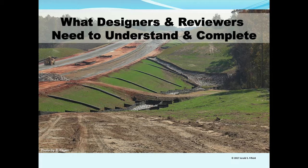So this is actually a great photograph because it shows a lot going on in it. And this is what we're trying to strive for: BMPs that are working in conjunction with the actual project itself. I mean, you can see they're working up here on the roadway, but they've already started stabilization. That's kind of the goal when I look to putting plans together, is trying to get that combination of sediment control with the erosion control aspects being done during the construction process.